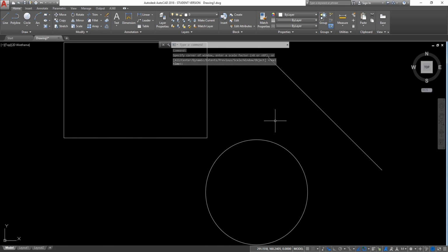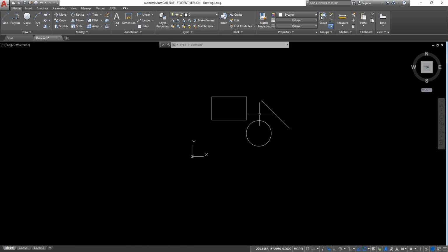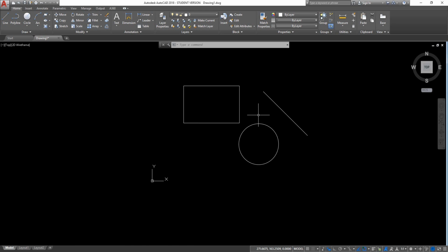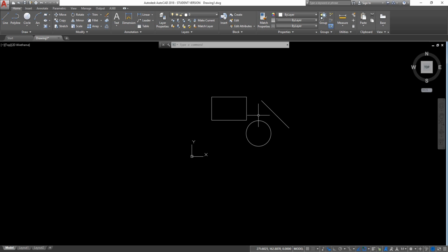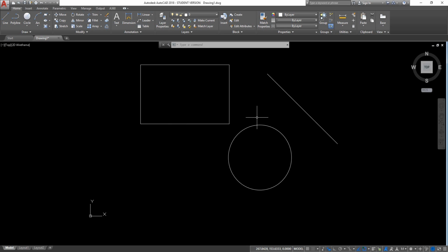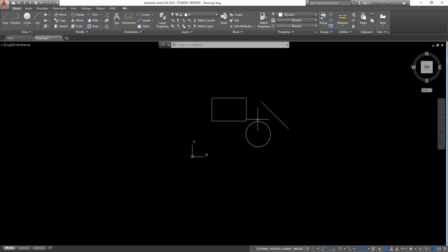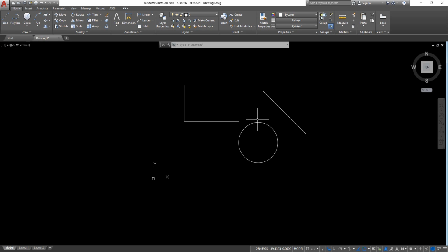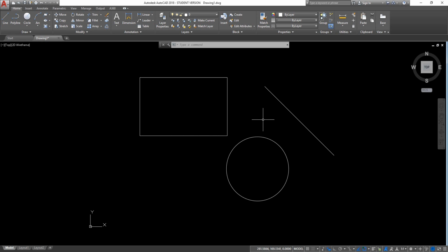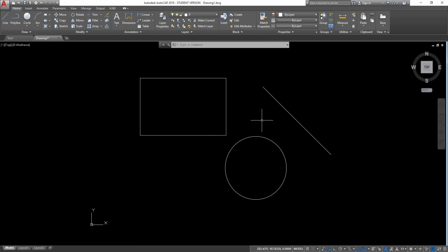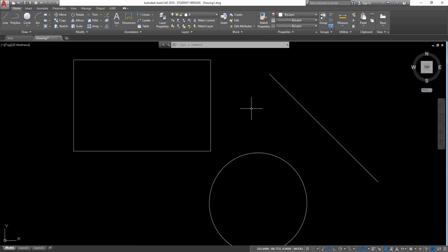And the last way of doing these zoom and pan commands is with the wheel of the mouse. Okay. In some cases, when you turn the wheel down or backwards, it makes a zoom out. And sometimes when you turn backwards, AutoCAD can make a zoom in. That differs in the mouse. It's not in AutoCAD's configuration, it's in the mouse. So just turn it to discover what kind of mouse you have.